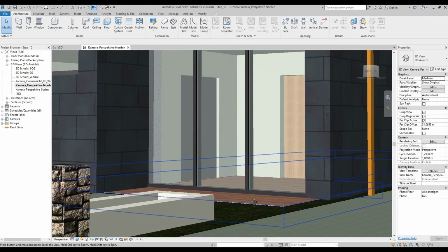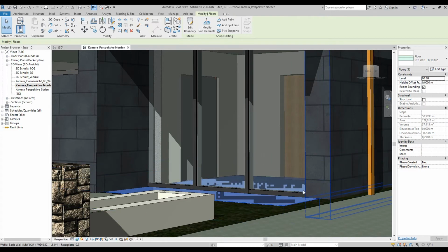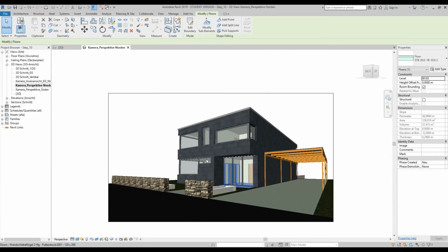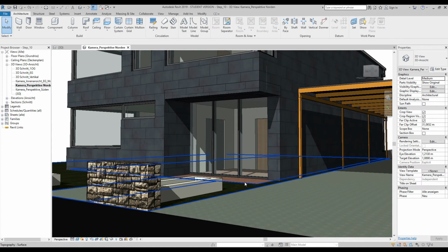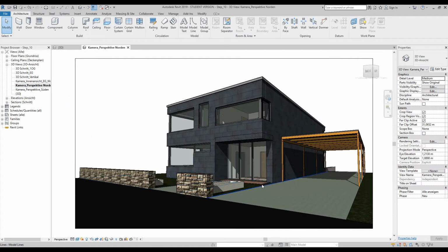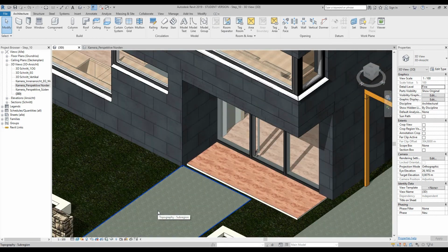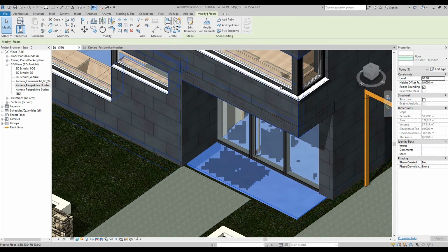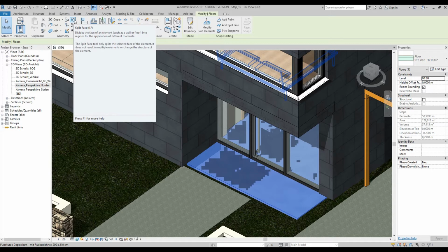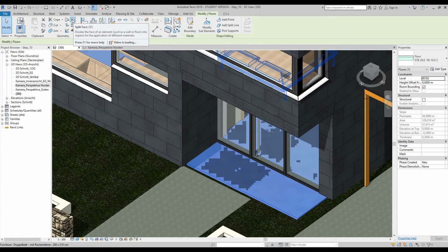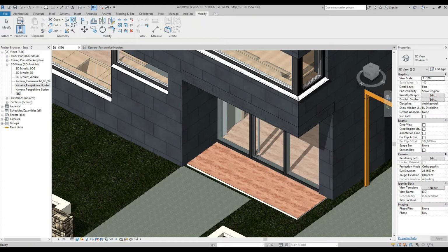Now I'm not sure if you're able to view this properly, but if you zoom in slightly to the entrance hall, you'll notice that it's one particular floor that's actually coming outside, which is not great. Now usually you would do a separate floor for the outside, but I'm going to teach you a little tip to be able to cut it and add paint to it. So if we go back to our 3D tab, and then if we rotate to the area, and then if we select our floor, the user interface will turn green, and over under the geometry section you'll see what looks like an old-fashioned TV, but it's actually a wall with a little blue rectangle on it. So if we select that, and then if we reselect the floor,